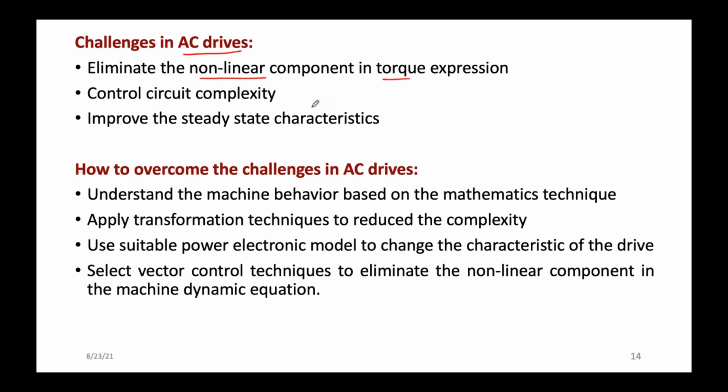Next, more state variables are involved in the torque expression, so control complexity increases. If control complexity increases, the burden on the processor increases, and at the same time steady state performance will degrade. That's why you need to put more concentration on the steady state also. These are the main challenges in AC drives, particularly.